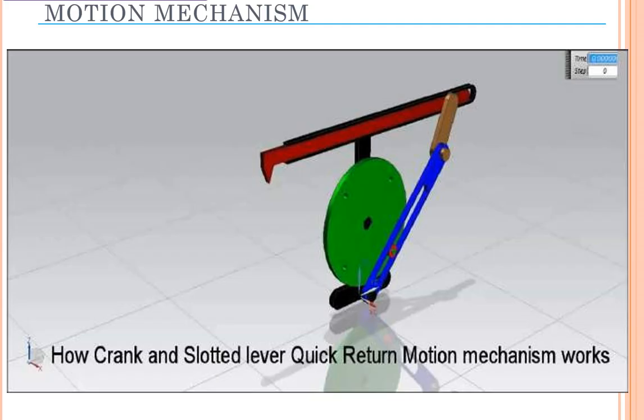So, continuation with respect to the previous mechanism. Further, we'll extend with different types of mechanisms with respect to the inversions. So, the quick return motion mechanism. So how a crank and slotted lever quick return motion mechanism works is...